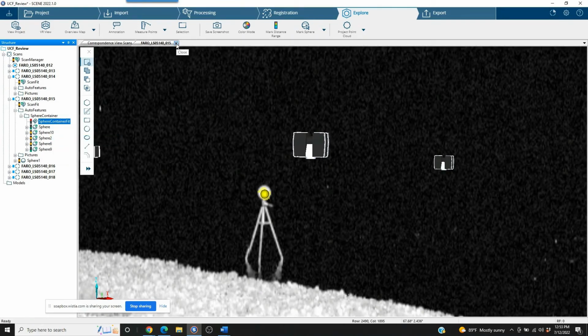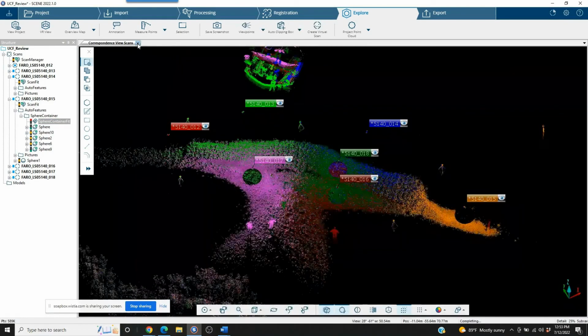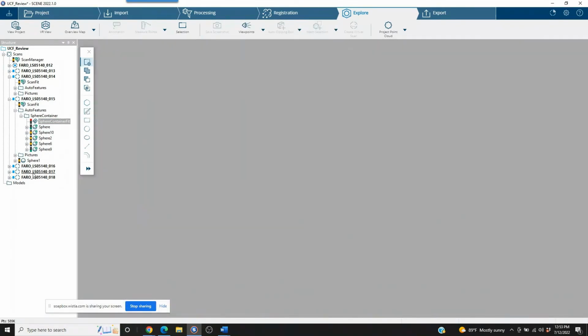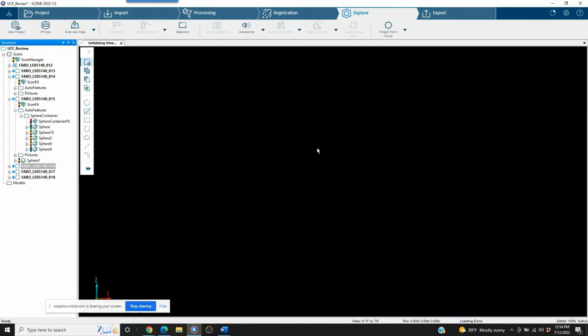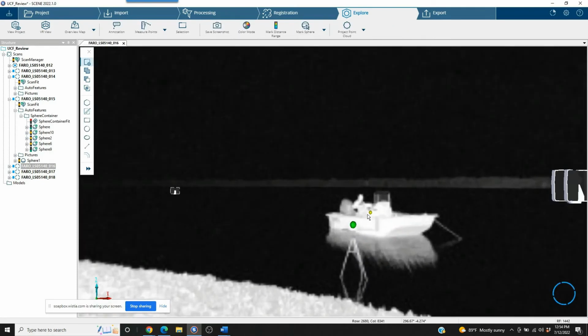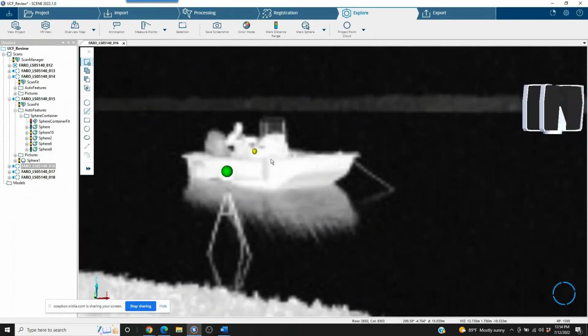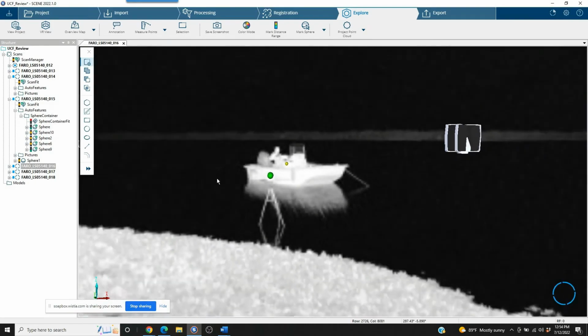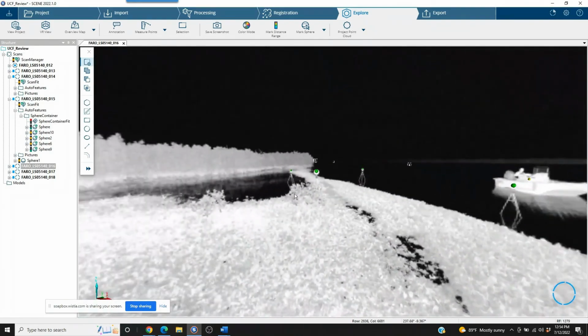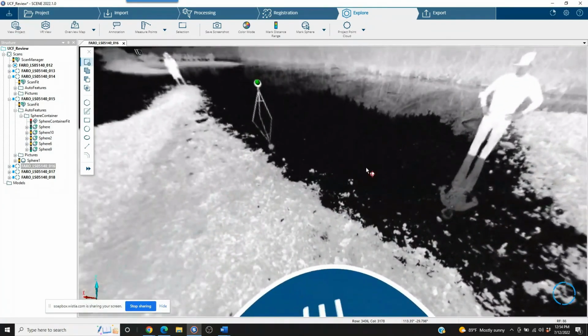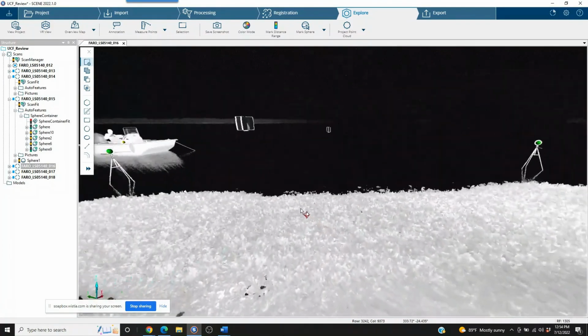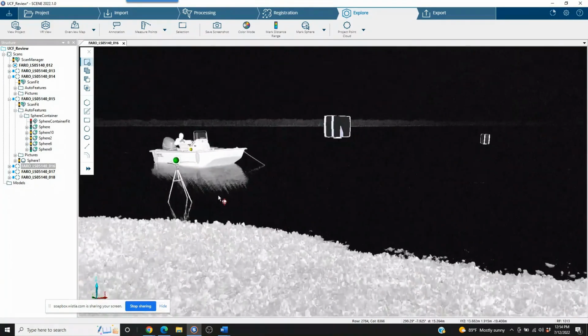And hopefully that will start to improve our accuracy throughout the entire project here. And again, we can go into each. I suggest if you've got a problem with your scan accuracy, that you go into each scan and eliminate the bad targets, and also add in ones that may not have been picked up.